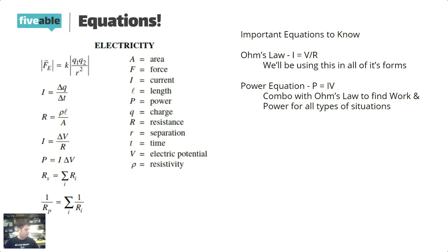For example, me grabbing onto my cell phone cable here and connecting the pins, I am actually letting a tiny amount, and when I say tiny, we are talking 10 to the negative 7th, 10 to the negative 8th amps of current, going through there. For all practical purposes, that's 0. But in reality, it's not.